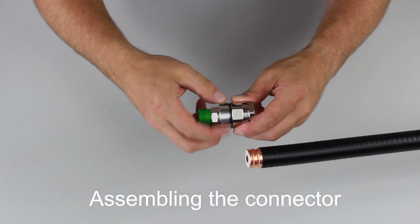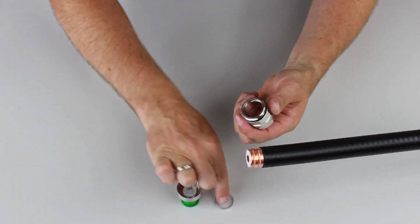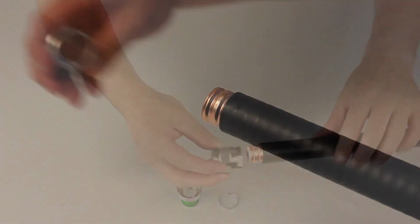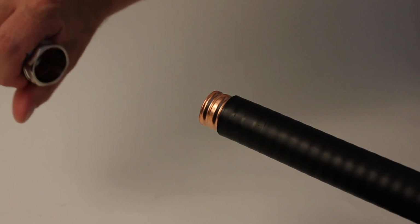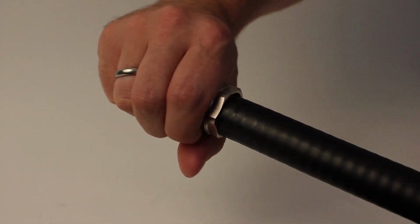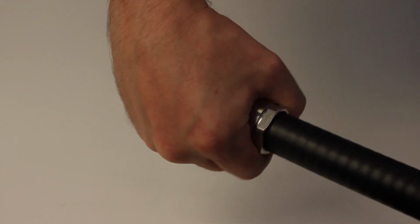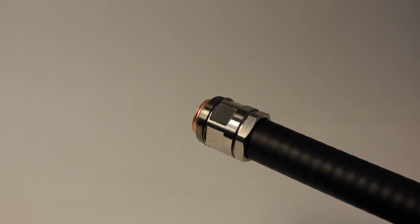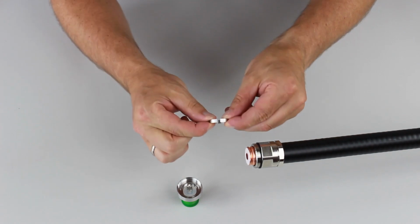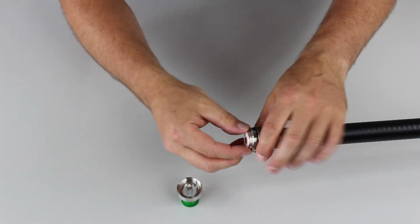Unscrew the connector. Make sure that you do not lose any parts. If necessary, slightly loosen the back of the connector so that the seal does not block the threading process. First, thread the back of the connector onto the cable, and if necessary, twist it slightly to prevent the seal from blocking. Push the back of the connector as far as it will go against the cable sheath. Then thread the slotted spring ring into the first trough of the cable.